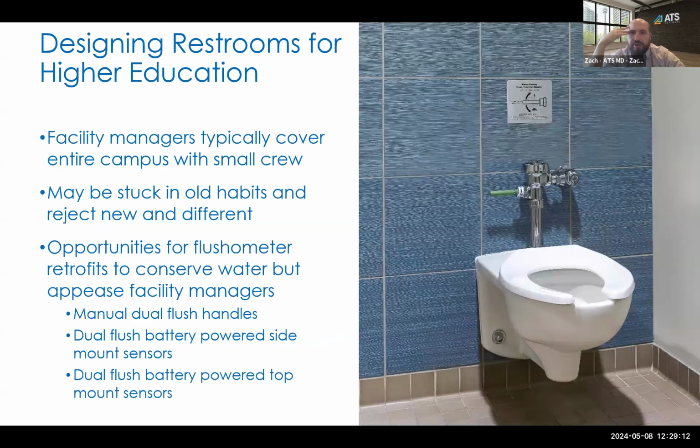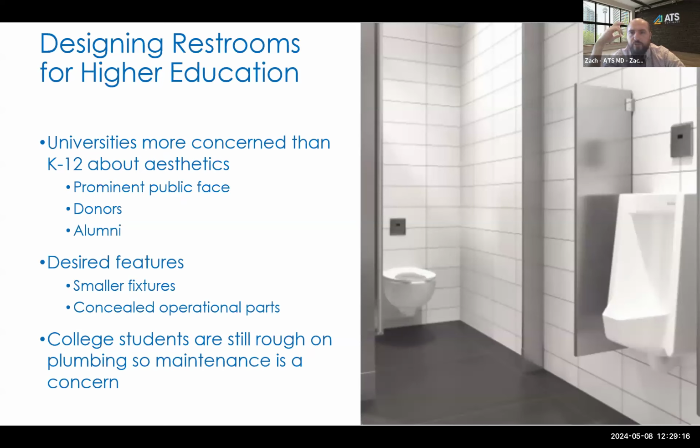I think it's just one comment as you're showing that concealed small wall box, like that little 4x4 faceplate. Aesthetics is an important aspect of design, but so is maintenance. So one thing to be considerate of if you are doing a small faceplate like that, make sure that you have a chase or access, which is not as common these days, a person access chase. So just be cognizant of that in your layouts of your design.